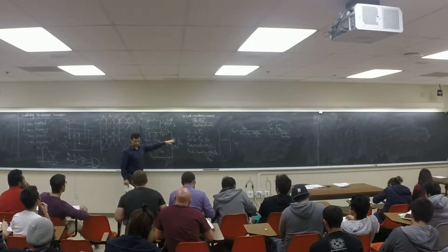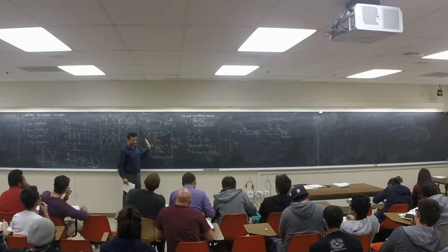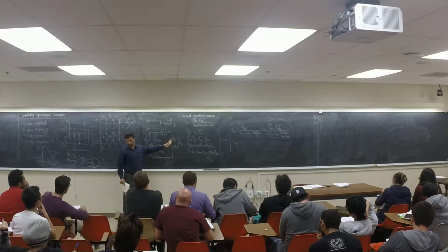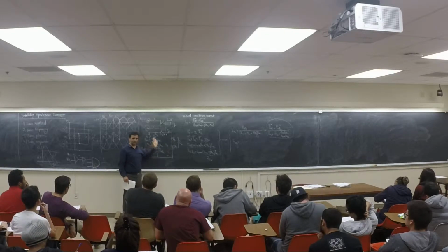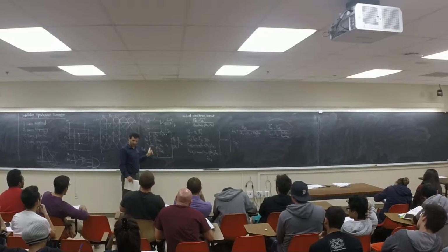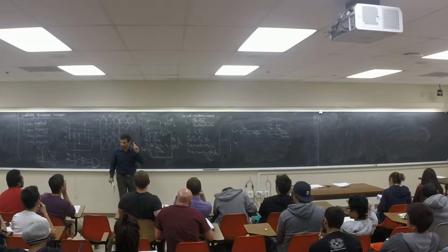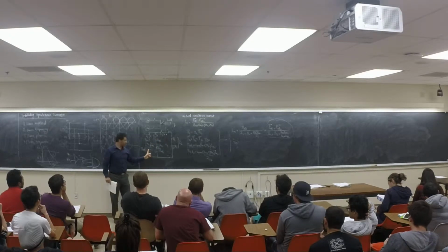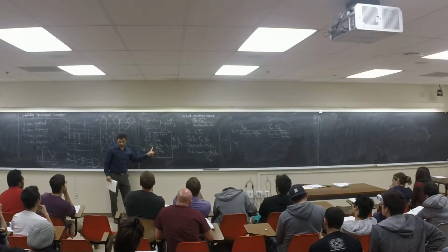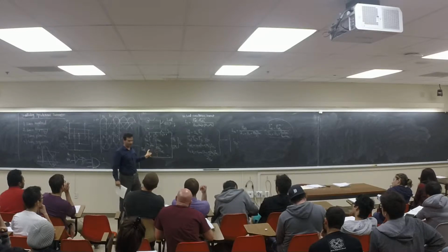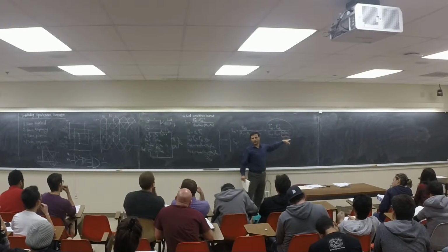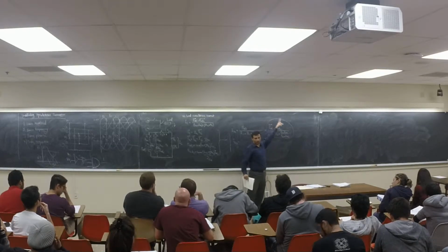Think about it. Then you have both loads, and these two you're not going to match exactly, right? Let's say we have 20 amps here. If we have 20 amps, this one is giving us 11 amps, this one is giving us 9 amps, right? So basically it's like that. This one is giving 10 and this one is giving 10, but there is one amp of circulating current here, right? So 1 plus 10 is 11, and 10 minus 1 is 9. So the better matched these two are, the smaller this one. This is the circulation current under load condition.